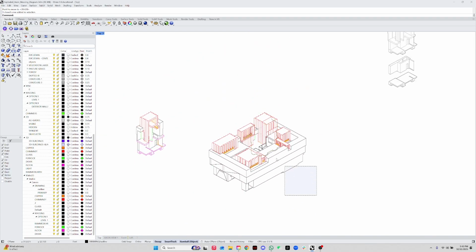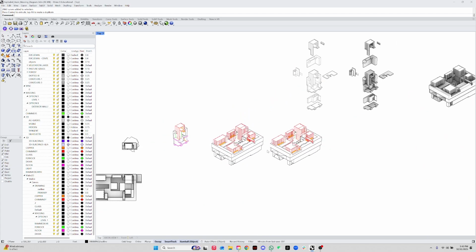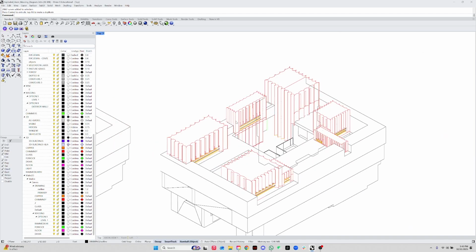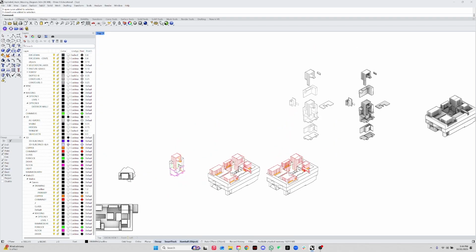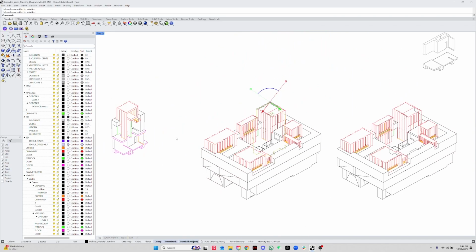Now, what I want to do is make another copy of this. So I want to have 2 copies, right? One copy is going to be so I can retain the information here, and then one copy is going to be so I can retain the information of the outside of this curve, so everything around it. So now we're going to want to make sure the curve that you're using is closed. If you have an open curve, the next step is not going to work. So please make sure that your mesh outline is closed completely.